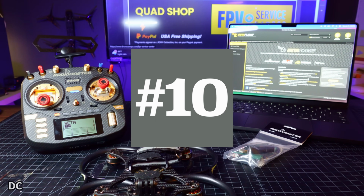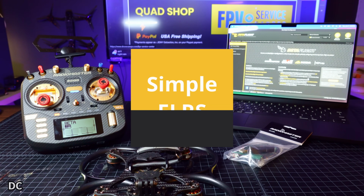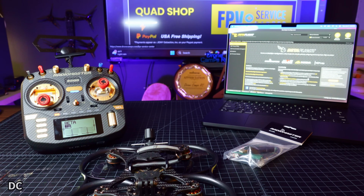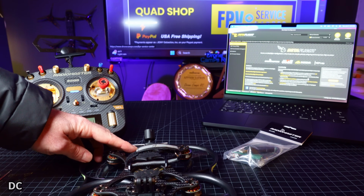Now, one of the things that people have the most problem with nowadays is getting the radio to bind up with an ELRS receiver. So ELRS radio to ELRS receiver, sometimes it's just not happening. Do I have the right receiver for my radio? You need to check out the radio version for the module, internal module or external module. The next thing you need to do is make sure you have the right version of receiver firmware as well.